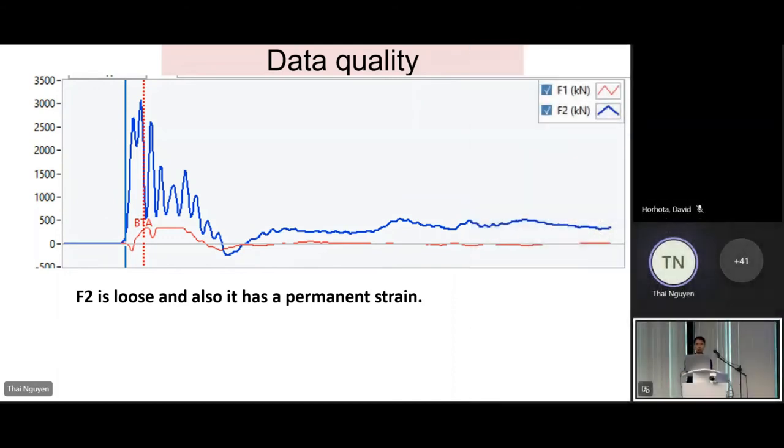In this example, it is only 7 inches, and the centrifugal pipe more frequently has cracks on the top than our FDOT solid pile. FDOT is a solid 18 inch, 24 inch, or 30 inch pile. You would almost never see a crack on the top of the pile unless it is small, but if it is small, the whole chunk falls off, not a crack.